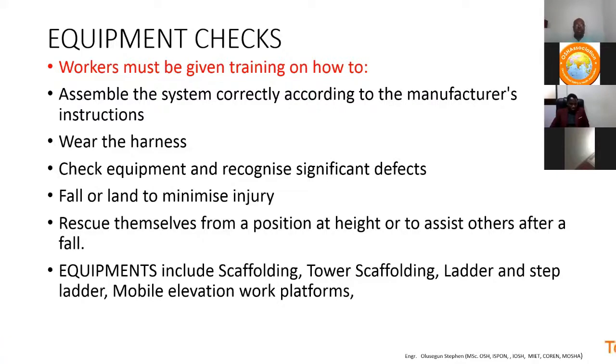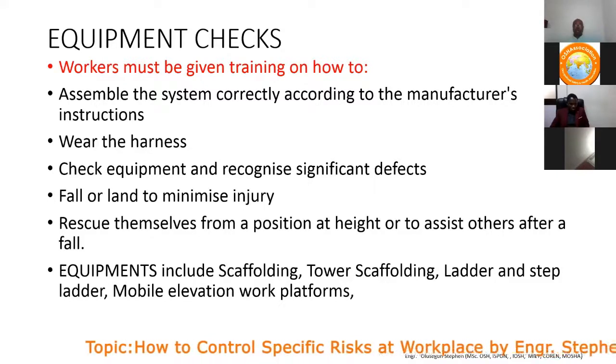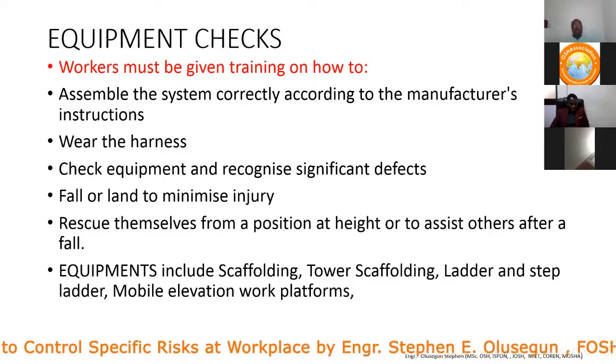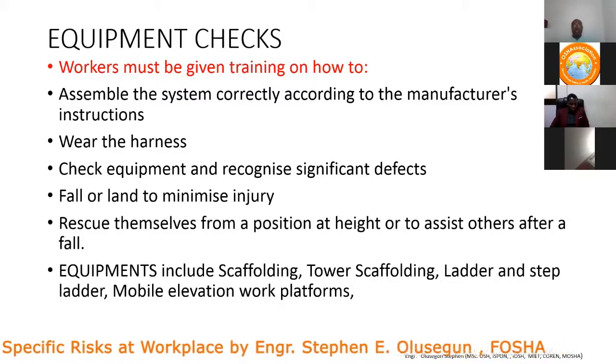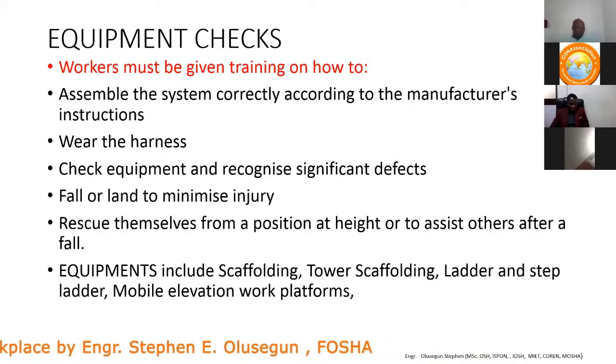Check equipment and recognize significant defects on it. Learn to minimize the injury in a fall, rescue themselves from a position at height, or assist others after a fall. Equipment includes scaffolding, tower scaffolding, ladders and step ladders, and mobile elevating equipment.